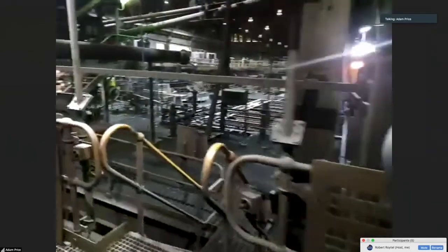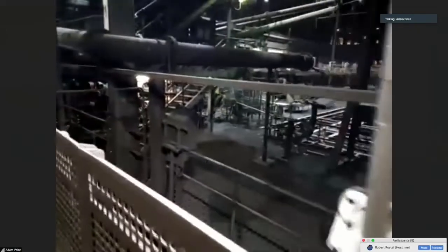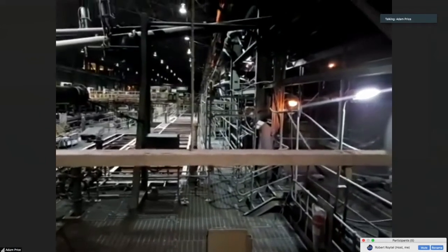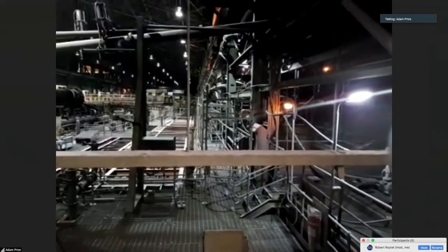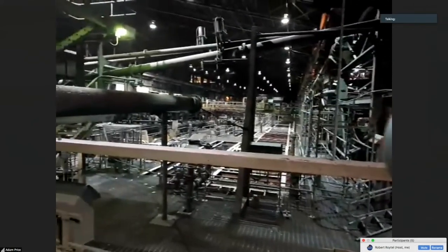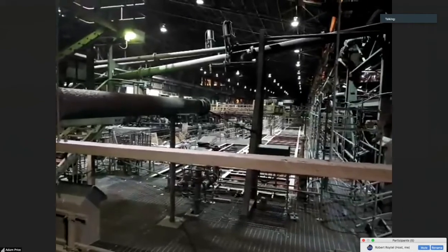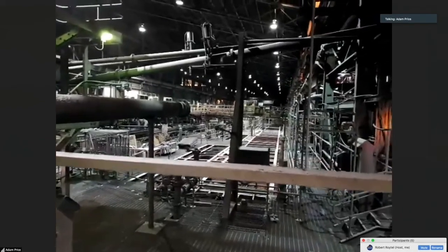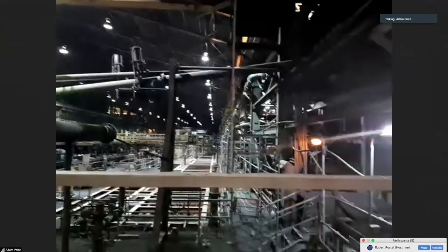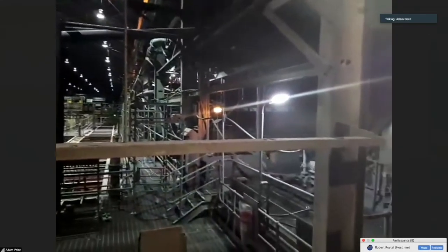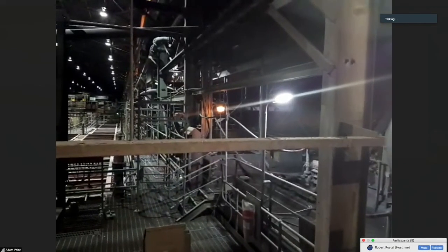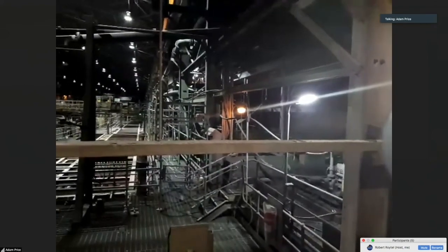Basically, what they do is clean the lips, wash the water mats, and check the downcomers. But aside from that, the Jameson cells need minimal attention. As you can see over here, if you want to compare the footprint of our previous cleaner circuit, basically the gap in the flooring, you can see just a portion of our old cleaner circuit. The cleaner used to be installed in there, and the re-cleaner. And towards the right end over there, we have the 3 columns, and towards the back, which you might not be able to see, we have the retreat cells.